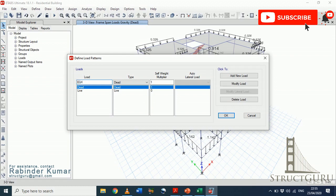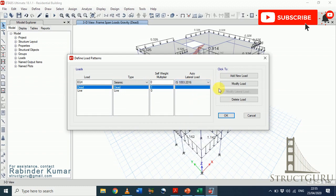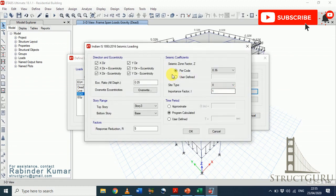So type EQX, choose seismic, select IS 1893-2016, click OK. Similarly, for earthquake in Y direction, type EQY, seismic, similar code, add new. Now we have to modify the parameters. To modify the parameters, click Modify Load, Modify Lateral Load, and uncheck all these parameters.